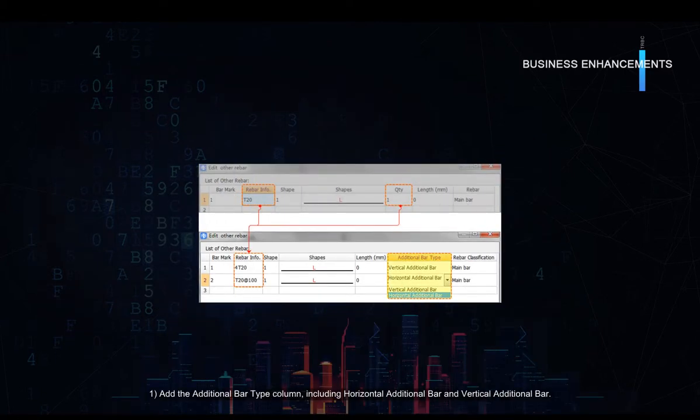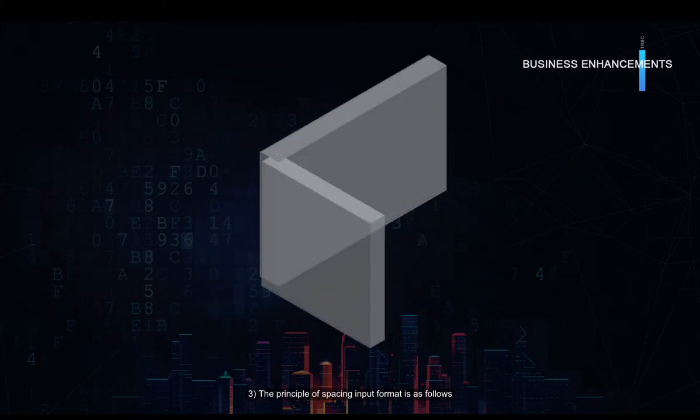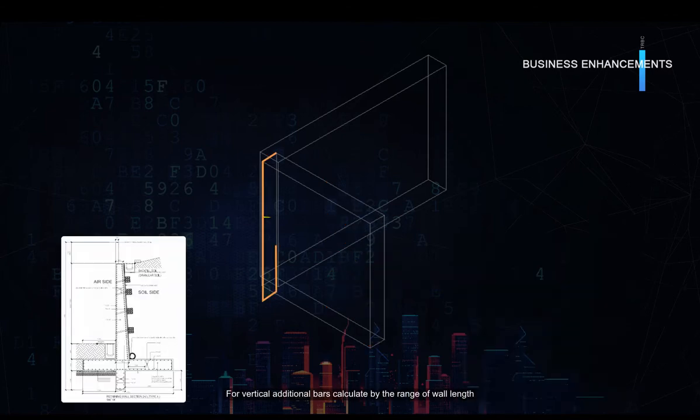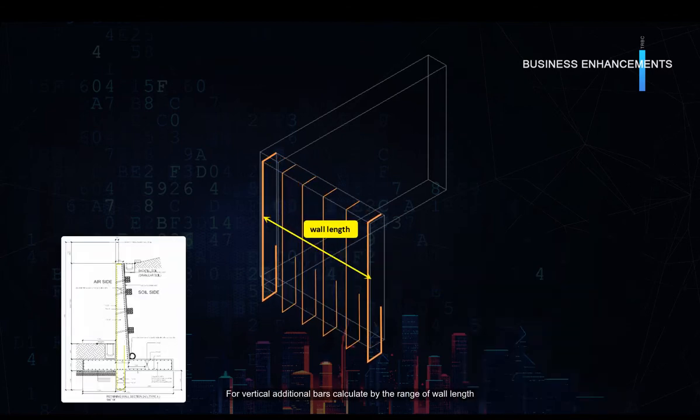1. Add the additional bar type column, including horizontal additional bar and vertical additional bar. 2. Enhance rebar input format, remove the CTI column, and in the rebar info column, you can input spacing and number. 3. The principle of spacing input format is as follows: for horizontal additional bars, calculate by the range of wall height. For vertical additional bars, calculate by the range of wall length.